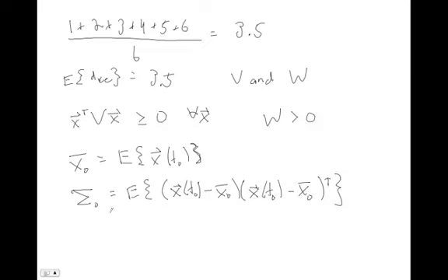This goes back to the idea that these are Gaussian white noise processes, where the measurement at any one time has no effect on the measurement at any other time. When we say they're mutually uncorrelated, we're saying that they don't affect each other. So when the disturbance is high, that doesn't mean the sensor noise is high. The disturbance could be high and the sensor noise could be low. The disturbance could be low and the sensor noise could be 0. There's no correlation between them.